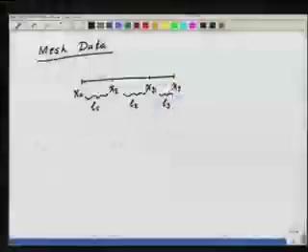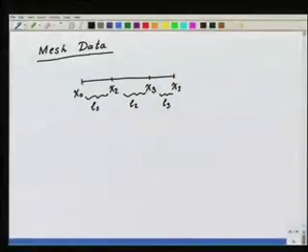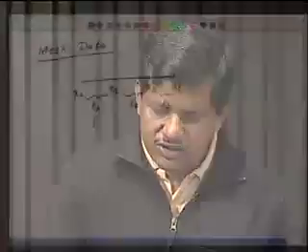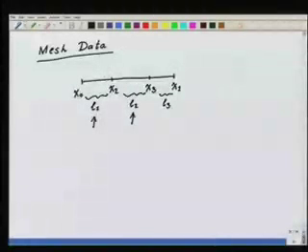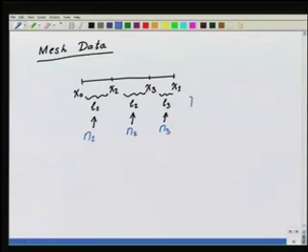Then we can ask the following question: in each of these partitions, how many elements we need to put. This is an input data which has to come from the user. The user may decide to put different numbers of elements in each of the partitions based on his needs, based on certain a priori information that he has about the smoothness of the solution and so on. So let's say that in each of these regions we are specifying the number of elements we need, N1, N2, N3, and we are assuming piecewise uniform meshes.